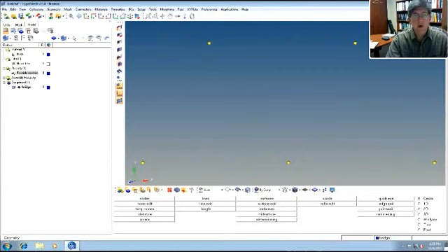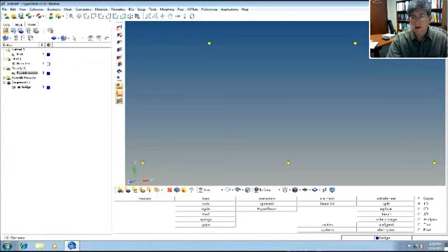All right, so now we're going to draw the elements. So now we're going to go to 1D because we're actually going to generate the elements. So the way it kind of works is in Hypermesh they have these names. These don't always correspond one-to-one with the Nastran element. So a bar might not always be a bar element. A rigid element might not always correspond to an R-bar element. Okay. The way you map these onto the specific Nastran elements is through element types.